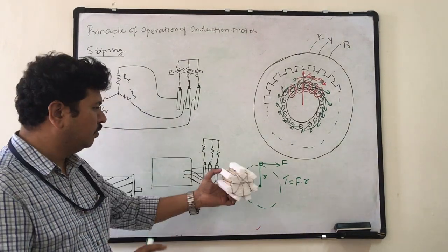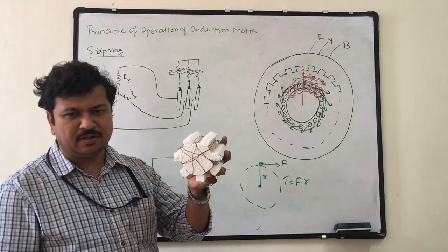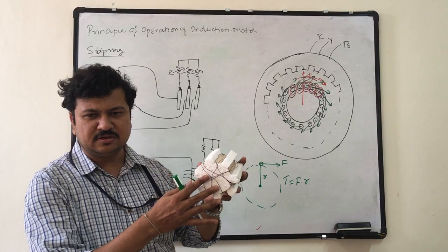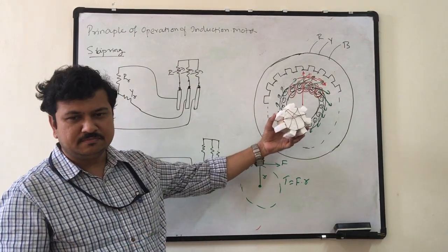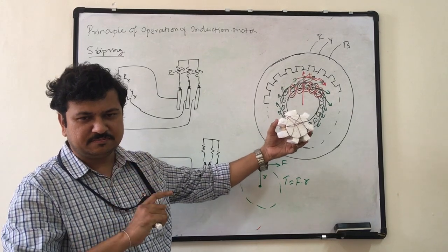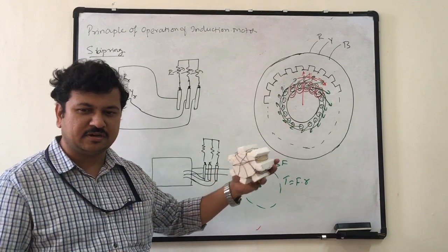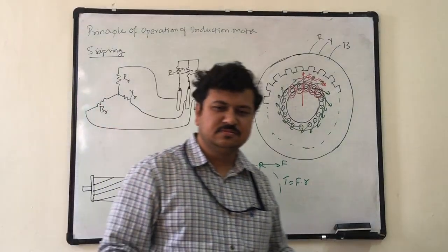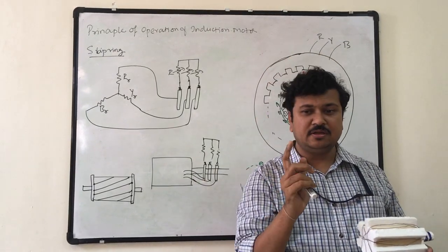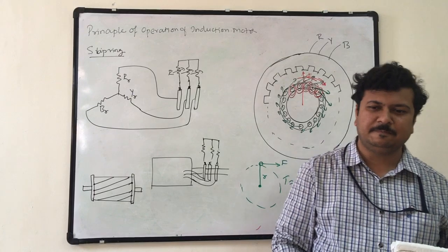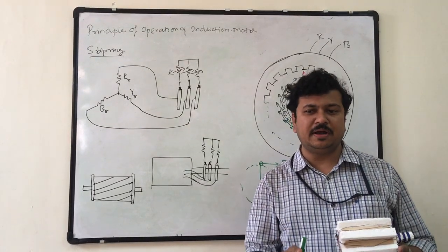Why? Because motors always operate with a cylindrical structure. The rotor part of the motor is always a cylindrical structure, and always kept inside the stator part. There is one exception to this, a motor where the rotor is outside the stator: our ceiling fan. If you open the ceiling fan, you will see that the outer part is rotating, the inner part is stationary.